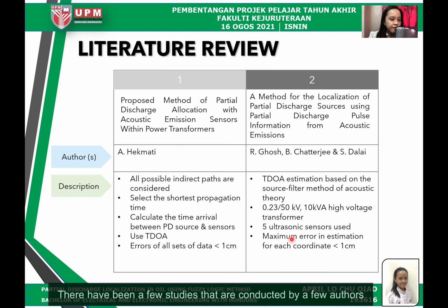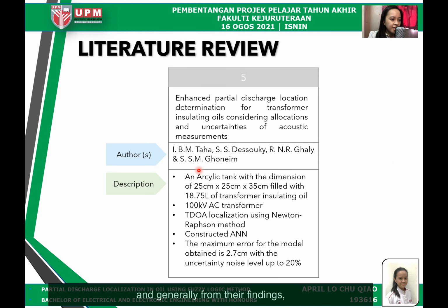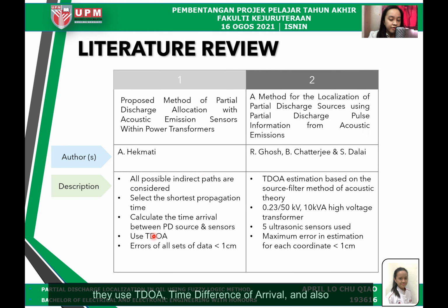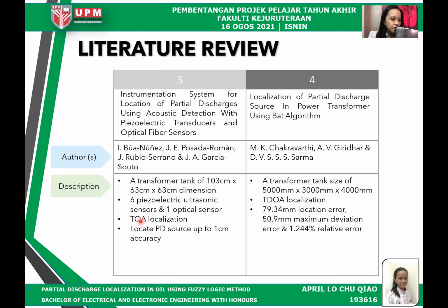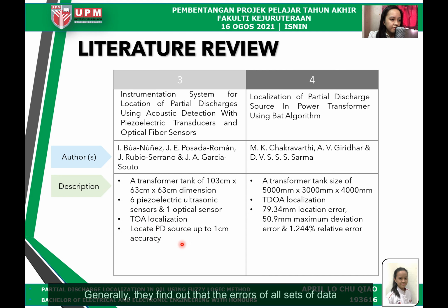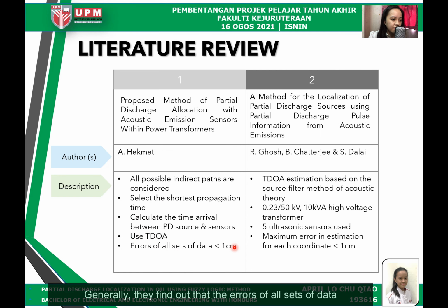There have been a few studies conducted by a few authors, and generally from their findings, they use TDOA, time difference of arrival, and also time of arrival, TOA, to locate the PD source. Generally, they find that the errors of all sets of data are within 1 centimeter.